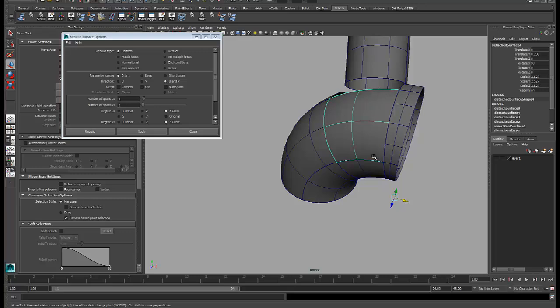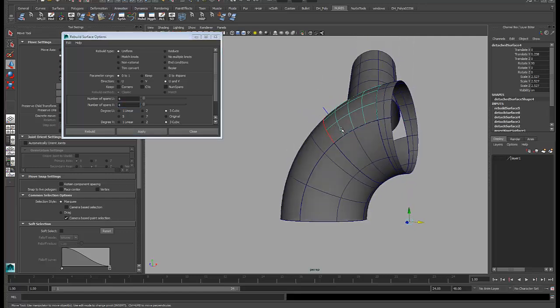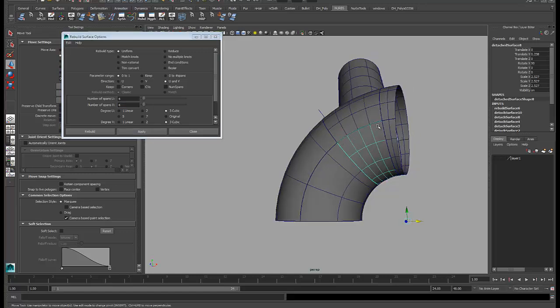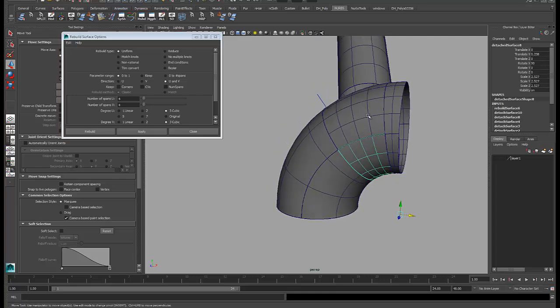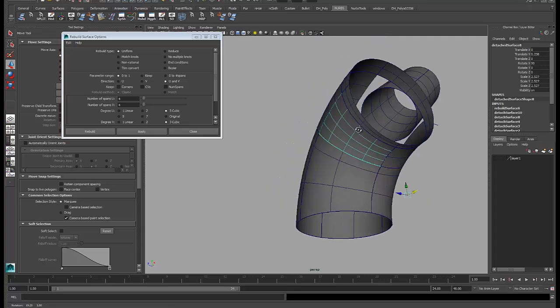In this direction here, let's just take a look and see which direction is which. So in the U direction, I need to have 4 spans because that's what I'm meeting up with over here. In the V direction, it doesn't matter, but I like to have 4 to work with because it gives me the most. And it's also going to make this turn into squares. So I'll make this one a 4 by 4 as well. So I'm going to go around and I'm going to make all of these now 4 by 4 because they have to be 4 in the U direction and 4 in the V direction because that's what their adjacent surfaces are.